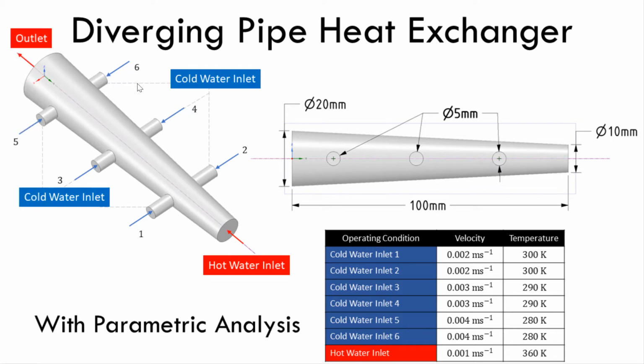The pressure is standard, that is 101,300 Pascal. The dimensions of the geometry are shown on the screen. A sketch considering symmetry for the diverging duct will be drawn and then revolved around its axis. Using plane view, circles are drawn and extruded across the symmetry.